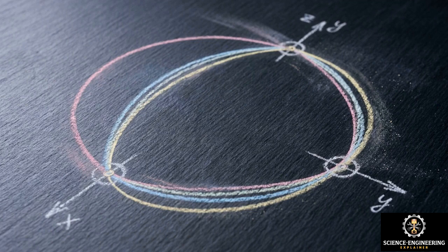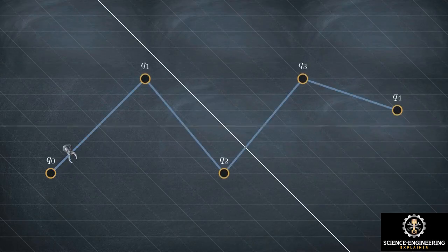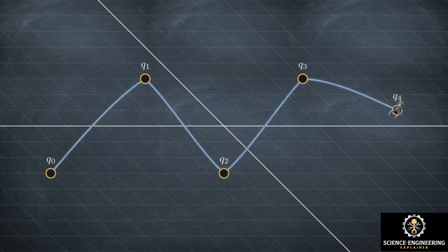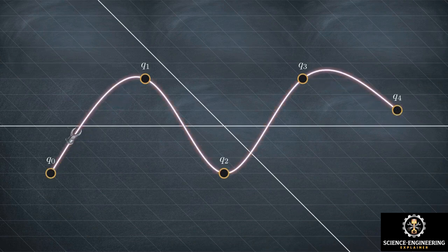To maintain velocity and acceleration continuity across multiple waypoints, planners upgrade to SQUAD, the spherical cubic spline algorithm. This elevates the path to C2 continuity. This path animation demonstrates how SQUAD functions as the SO3 equivalent of cubic Bezier splines. It removes the jagged linear segments, bending the trajectory into smooth, flowing curves that still intercept the target nodes.